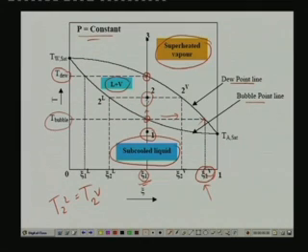So, the concentration can easily be obtained if you are drawing this temperature line, and where this line intersects the bubble point line, that will give you the concentration of liquid. And where this constant temperature line intersects the dew point line, that will give you the vapor phase concentration. So, by using this you can find out easily what is the concentration at different phases. It is interesting to see that the concentration will be different in the two phase region. And once you come back to the superheated region, again you will find that because of the conservation of the mass, the concentration again remains same.